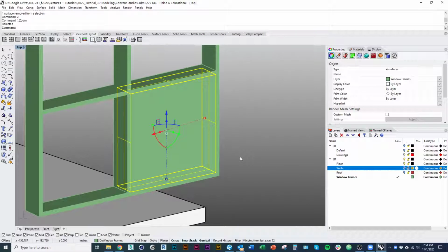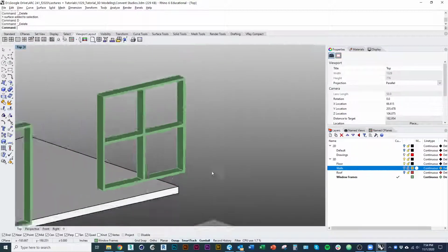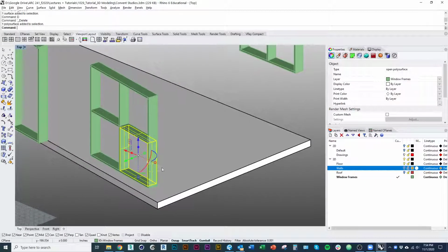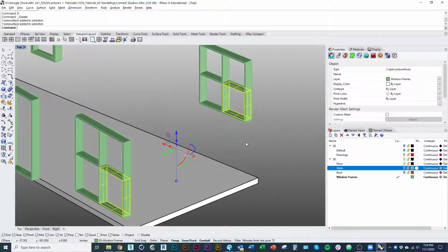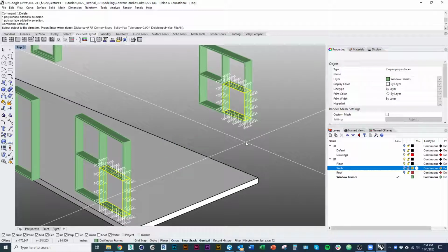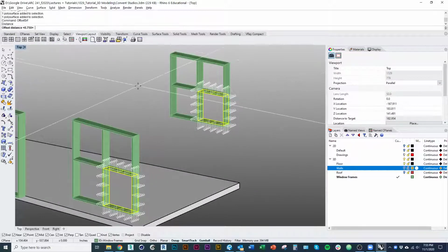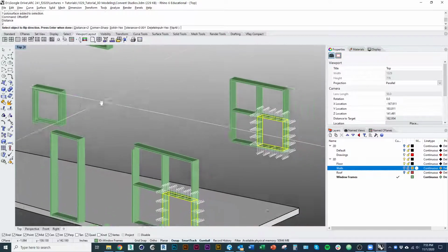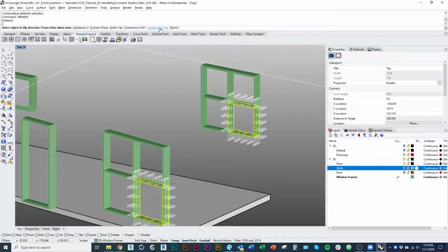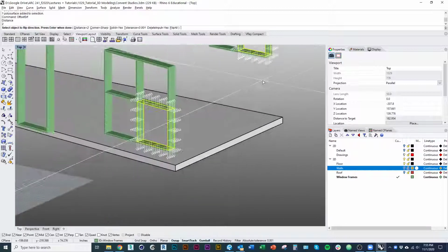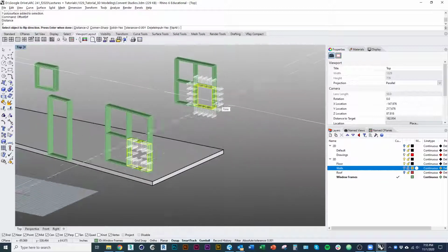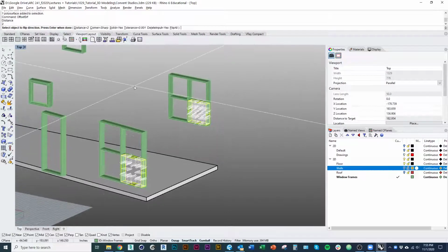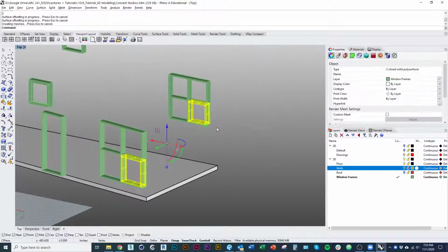So anyway, deselect the flat faces, the ones in plane of the window. Join the inside edges, delete. So just like before, I'm going to offset these guys. I'm going distance 2 inches. That's what we did over here. And you see, now, because of the way I modeled this, the arrows are pointing out, so I just need to click on each one to flip the direction that they're going to offset. And that's it, press enter.